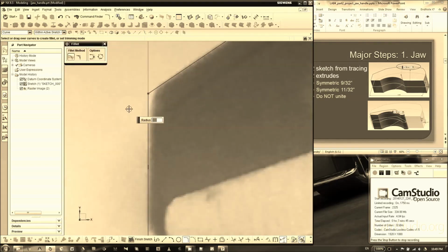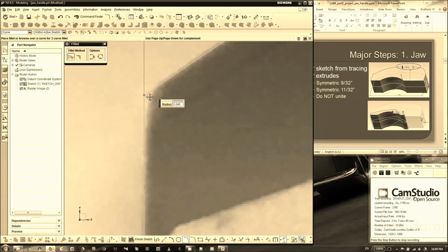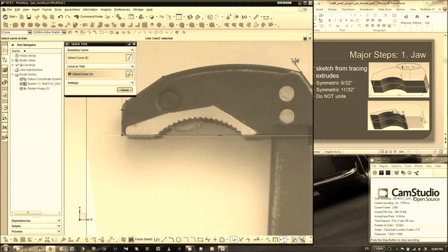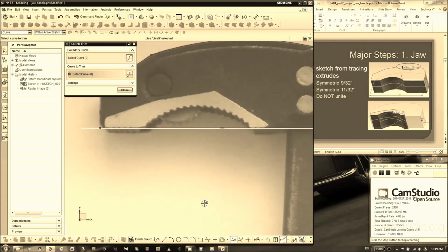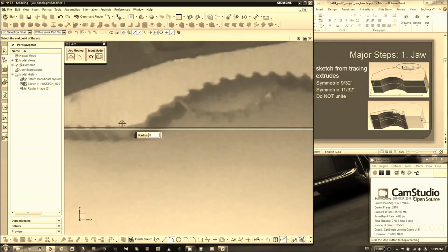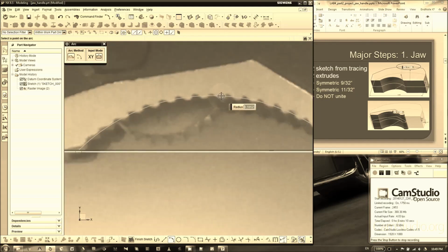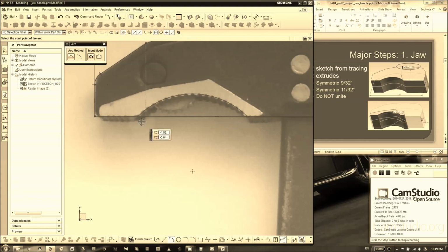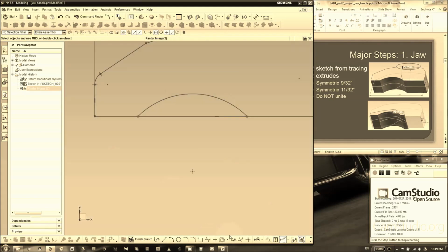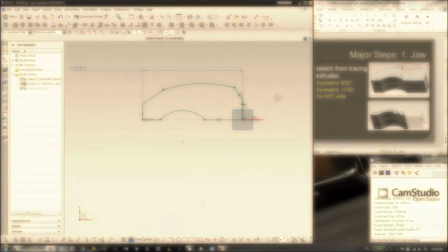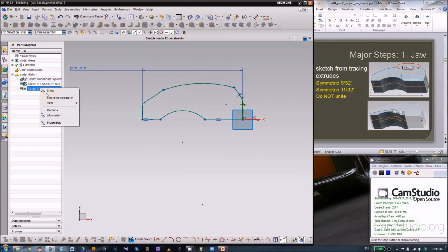And let's see, maybe a fillet for this. Well, okay. Then I'll just trim off those. And yeah, still need to put this arc here. So from here to about here, and I'm gonna make this to the middle of the T. And by the way, if you want to, you can put T on this. And still, I'm gonna cut the one in the middle. Let's hide the raster.